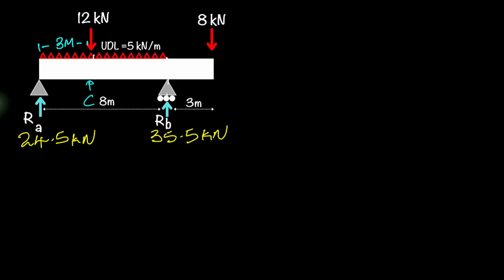Okay, so for the bending moment, we're going to take a section at each key point, and then we're going to sum the moments of everything to the left of the cut. So just as a key reminder, I think we have done this a few times, but the moment is equal to force multiplied by the perpendicular distance. So then I'm just going to use the purple line as my cut. So if we start then at A right here, that's my cut.